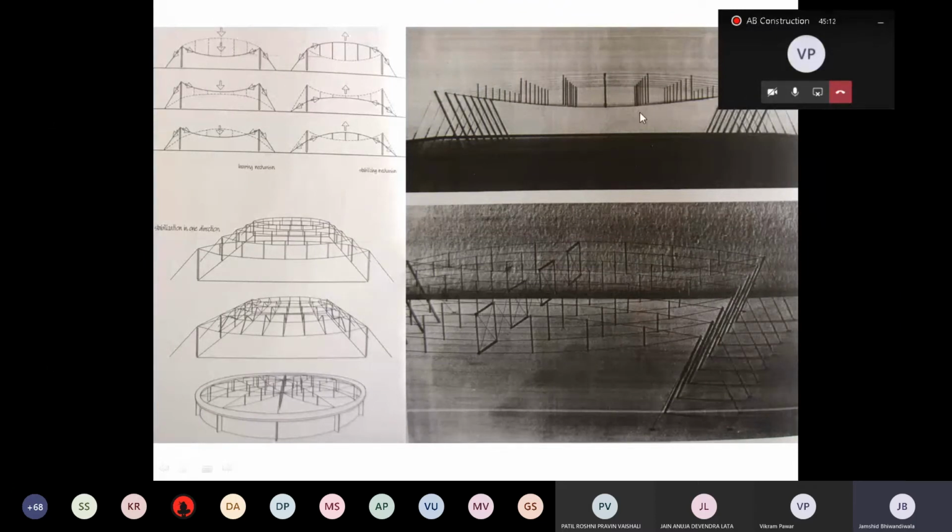So the truss comprises the cable-like tension members and vertical compression members, thereby helping in very large spans with no internal support. So you can imagine this. The span is large. It's as good as putting a truss across. The only thing, you're making it as lightweight as possible because you're using a cable and using the dead weight of the cable to help it in some sense by strutting it and creating what is well known as a bowstring truss. I hope these concepts are clear.